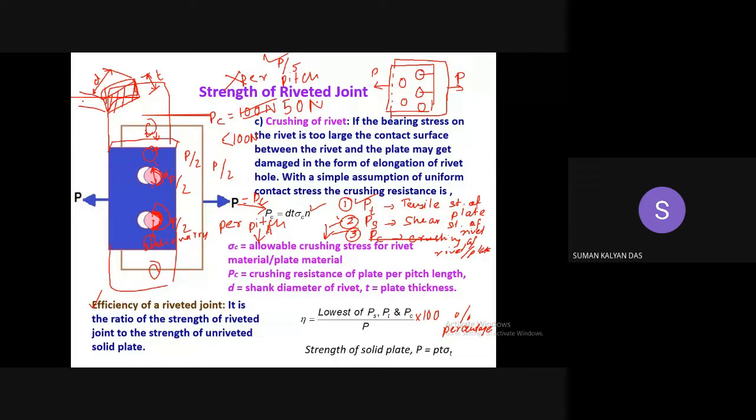Understood? When we ride an elevator or lift, although a limit is written, say for 5 people, the elevator can actually take 10 people in reality, but that margin is kept for safety. So this is an add-on factor of safety type of thing. So the reliability of the per pitch approach is much higher than the other approach, where we divide by the number of rivets, right?